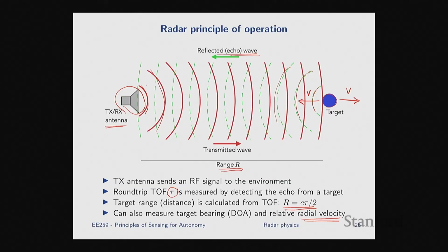So the next thing we're going to study: we talked about electromagnetic waves and how they propagate, Maxwell's equations. So right now, if an antenna geometry is described for you, essentially you can find the E and H fields that are radiated from it. How do you do that? First, you do that integral that finds the magnetic vector potential A from the current that is on the antenna. And then from A, you can find your E and H fields, and that is basically your radiated electromagnetic field.